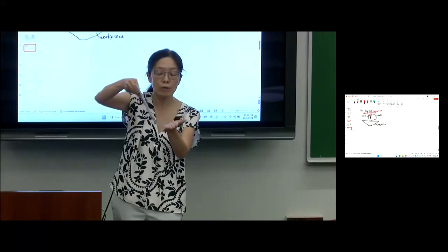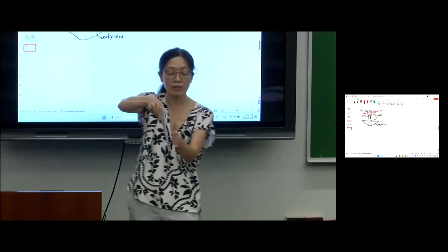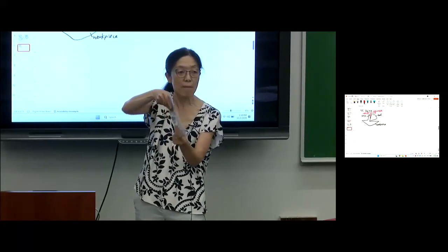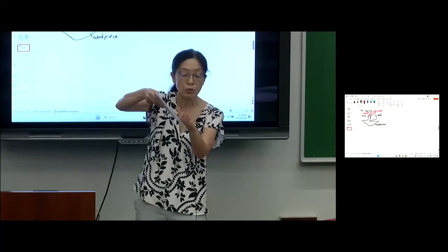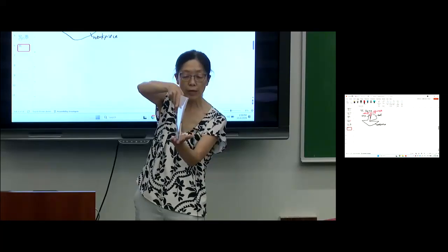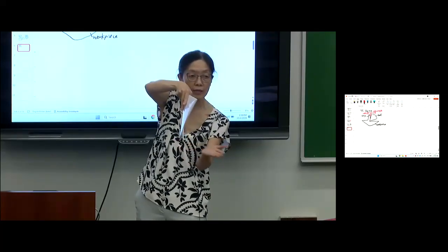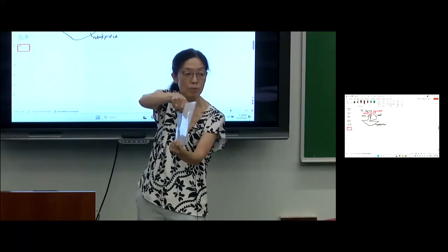That's why, to give this diamond or ceramics tool toughness, the material you cannot change, but how you contact, right? Make this tool contact against the workpiece. So that's why go like this or that. And you can just kind of support, or prevent it from chipping.